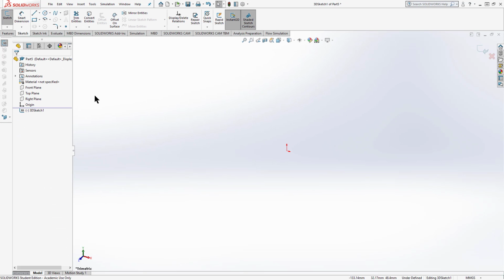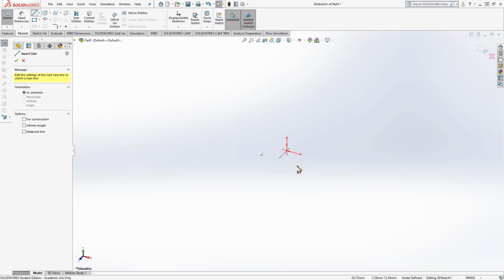You're going to notice right away when I choose the line tool and I pop into the sketch, I got a very different display here. So you can see that I've got a little glyph that still works just the way it worked before in a two-dimensional sketch, but I've got this funky little red crossbar orientation. And what that's showing me is that if I sketch right now, I'm sketching in the YZ plane down here on my trident. So the way I can cycle through planes is if I hit the Tab key, I'm now in the YZ, and now I'm in the XZ.